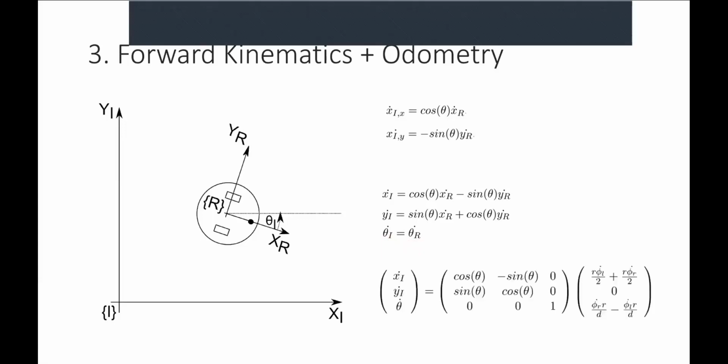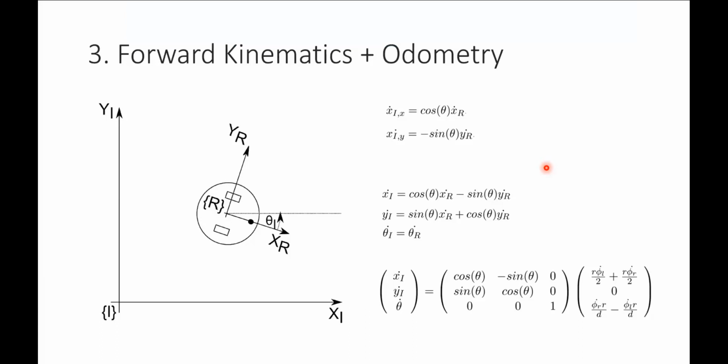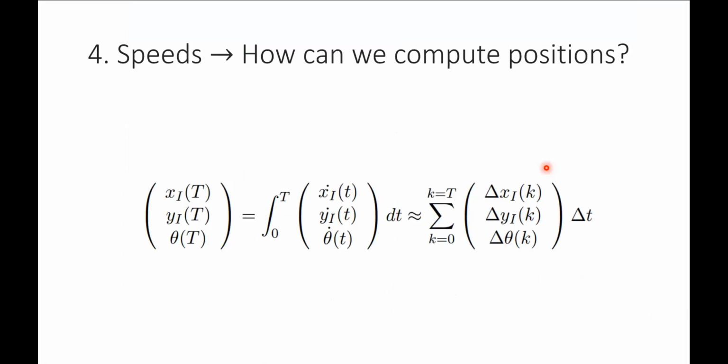And so we wrote it out this way as a more compact representation, but this is the same thing as this. And so you've hopefully implemented all of this by now. And the key insight here is that if we can figure out basically how far your robot has moved over the last piece of time that's gone by, so in this case, one sim time step, then we can just add those up over time and we figure out where our robot's gone. So that sums up where we've gotten so far.